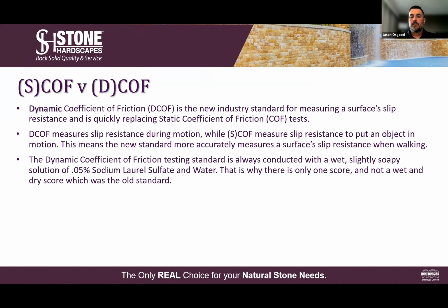The DCOF testing standard is always conducted with a wet, slightly soapy solution of 0.05% sodium lauryl sulfate in water. That is why there's only one score from a dynamic coefficient of friction. As with the static coefficient of friction, we had a dry score and a wet score.